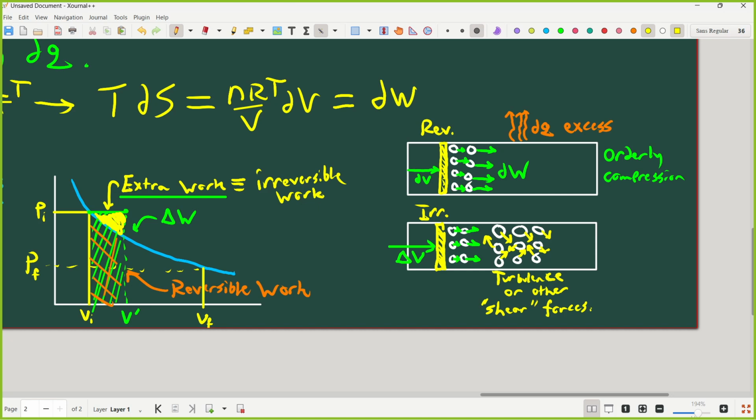Okay, so ideally, the easiest way, as in the least energetic way to compress a gas, is to do it reversibly. Right? You want to move smoothly along the curve so that you're not doing any extra work because you're causing turbulence or other dissipative effects in the fluid. Any questions about that? Okay. That's really all I have to say about isothermal expansions.